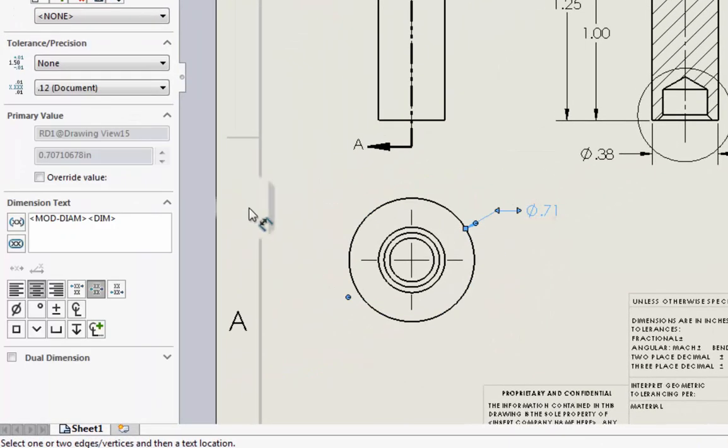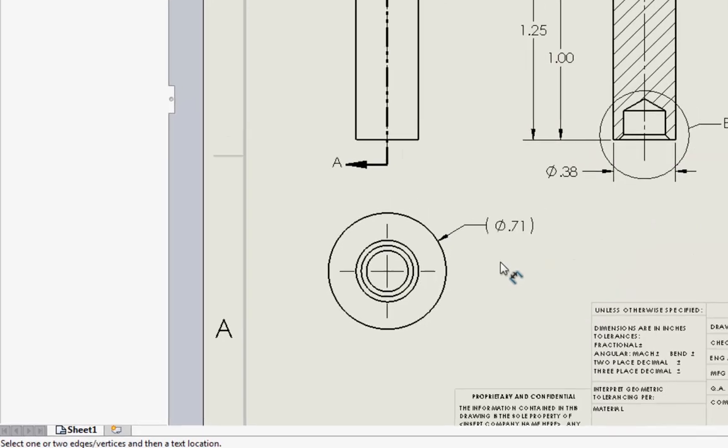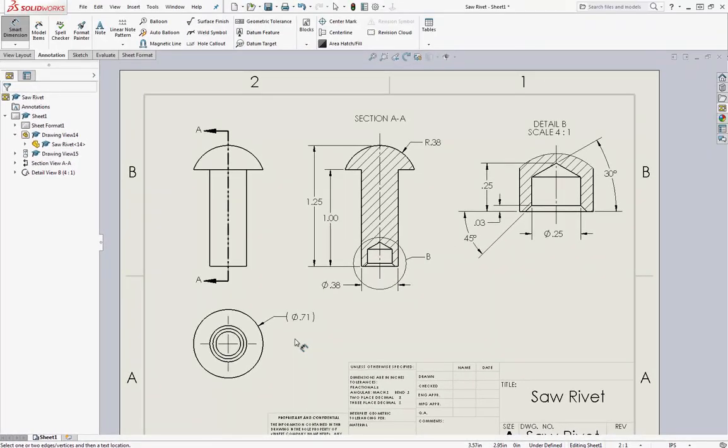We're going to call it a reference dimension, and we're going to put it in parentheses. If you put something in parentheses, then it's not a dimension that you absolutely have to have, but it might be nice to identify to see if it can help out. Whereas if you had just given the drawing like this to whoever's making the rivet, they might have to do a bunch of calculations to figure out what that's supposed to be. Why not make it easy for them? Okay, so there you go with the reference dimension. Now, sometimes it might be necessary to change the direction of arrows.